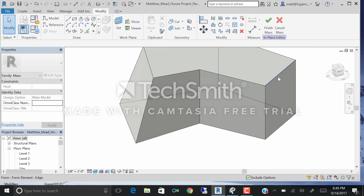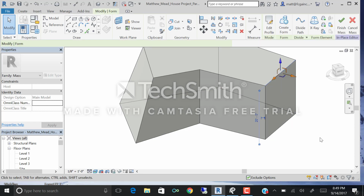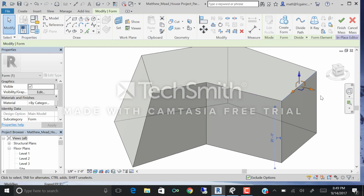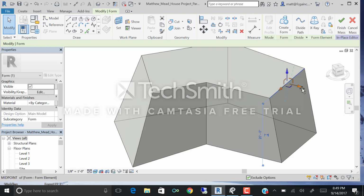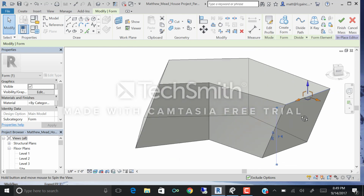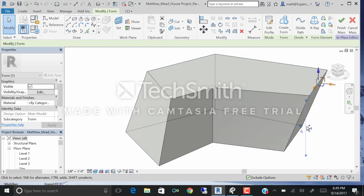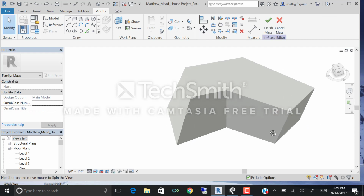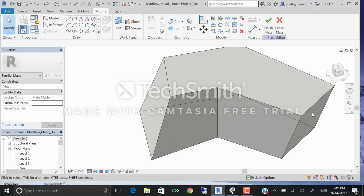So unlike a corner, we can also select an edge. If I select this edge, I have the same freedom to manipulate my massing any way that I wish. I can move the wall in. I can also move the wall out, and vice versa. I can continue to stretch or push and pull that shape until I get the look that I'm going for.